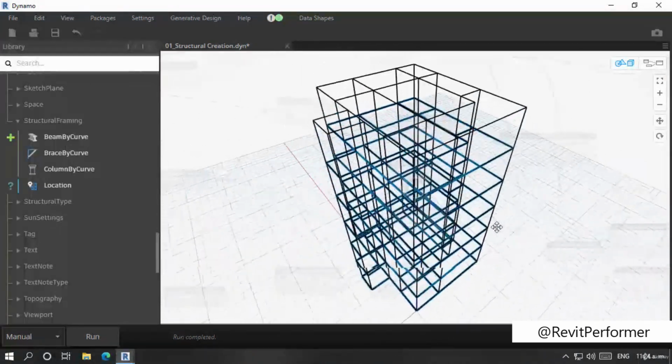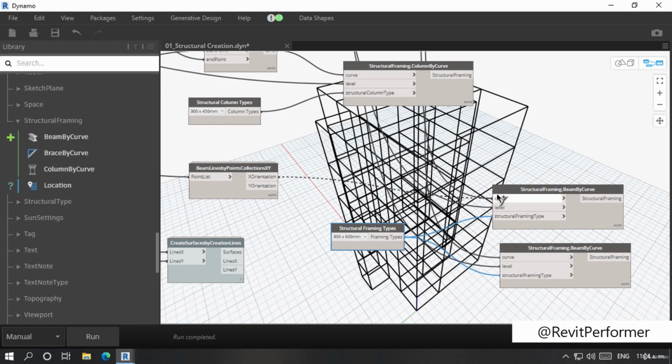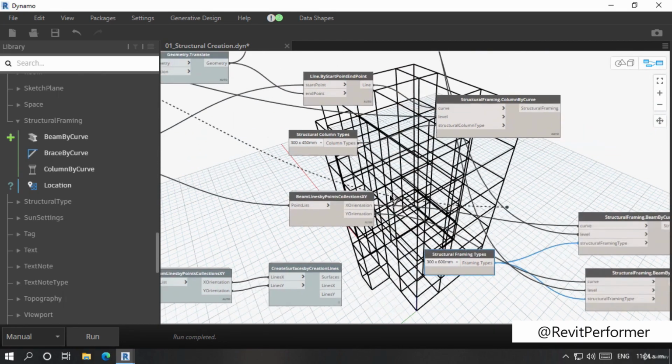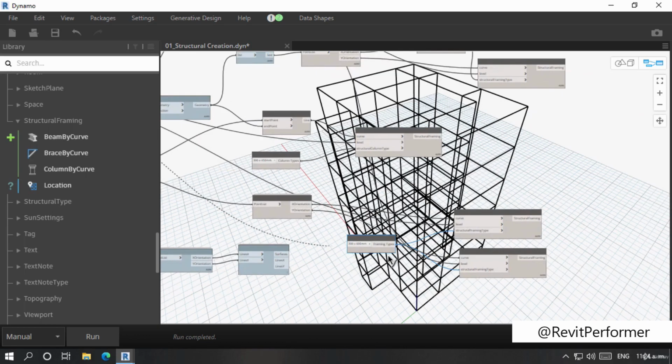It's using just the lines below the walls. So we'll go orientation on curve, orientation on curve. And the levels list needs to be complete levels list because they need to go both ways. So let's create.